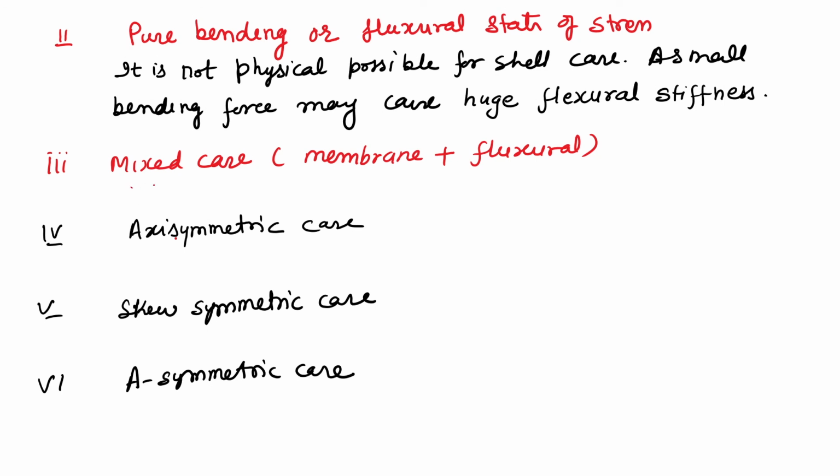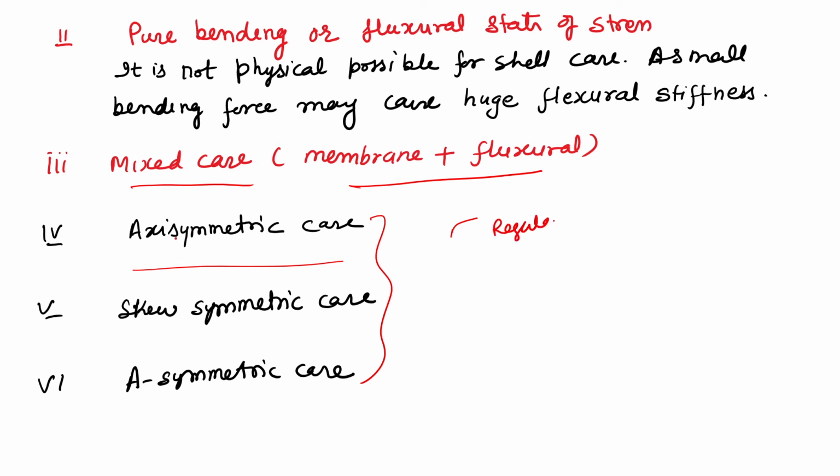Then the mixed case, which is more complicated, and then the case of axis symmetry in the loading. Because of the loading, the equations also get simplified, skew symmetric and symmetric. Even till date, the most generalized shell is not solved. They are mostly regular shells, which we call surfaces of revolution, like cylindrical shells and spherical shells. The structures are made out of that.